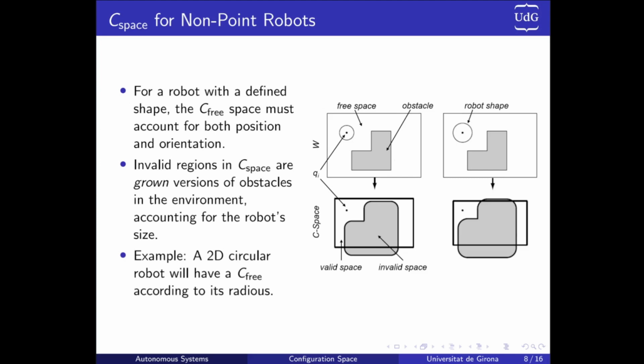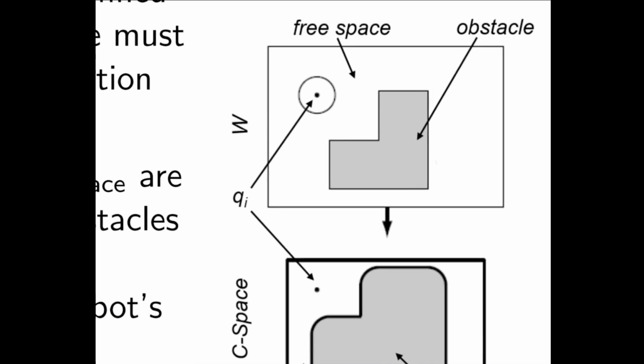the description of the robot and the description of the world and the free space or the C space that we can use is not the same. In this case, you can see that if the robot has this shape, then what we can go to is all the white positions, but not the gray ones, because although the center position will be free here, if I draw here, if I put this robot in this position, although this position seems valid, because the robot takes all this space, the robot will be in contact with the obstacle.